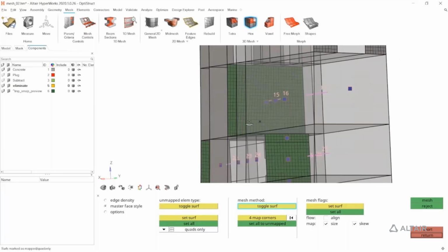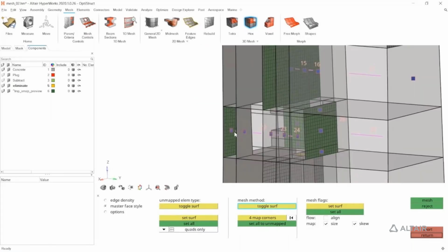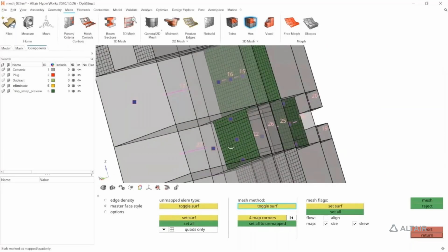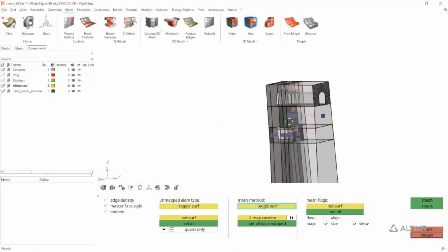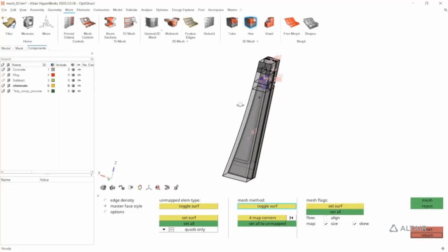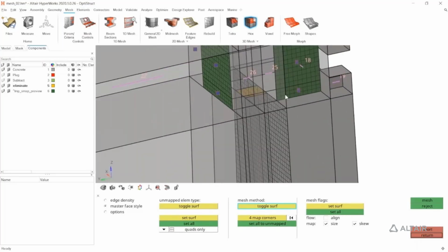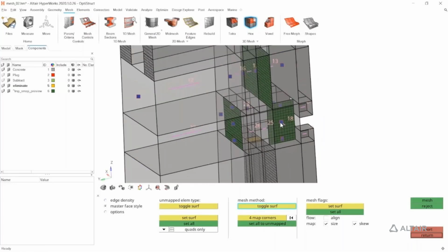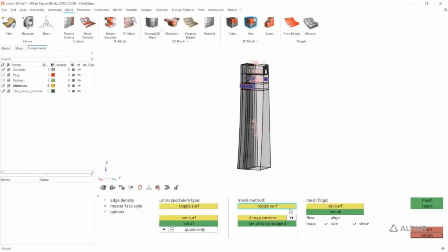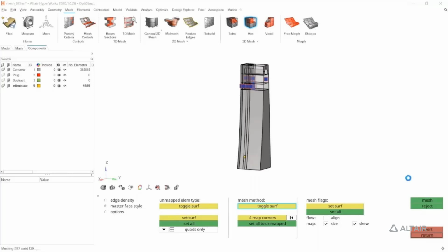If we zoom in, we see the different surfaces of the cutting planes. And these are the source surfaces, like the 2D mesh surface used to start the extrusion path. If you need to change or reduce the mesh size, you have ways to do so. You have the same tools to create the 2D mesh for a portion and be more detailed. This will be very fast and clean to make the new mesh. And we can zoom in and zoom out to see the different plane directions.